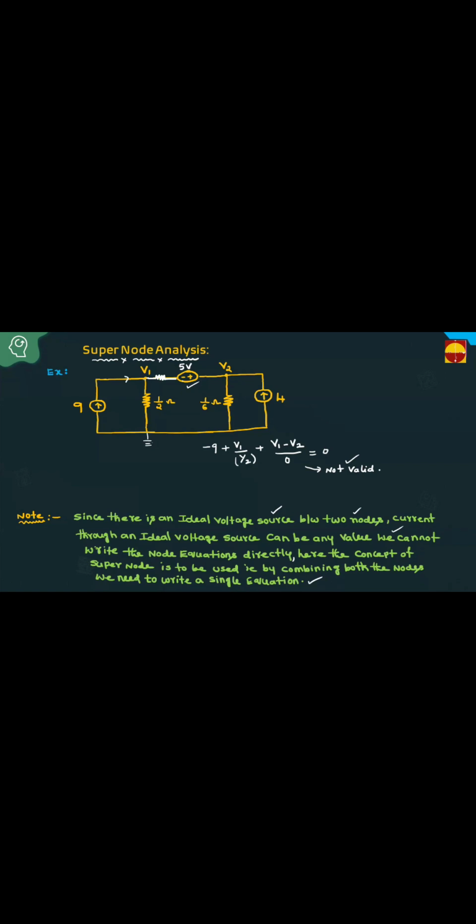But no need to go for that much lengthy procedure. Because in the normal case, we can easily solve just by applying nodal analysis at V1 and V2. But in this case, surely you have to apply supernode analysis. If resistance is not present, you have to apply supernode analysis. If this resistance is present, you can apply supernode analysis; even normal nodal analysis gives the same answer.